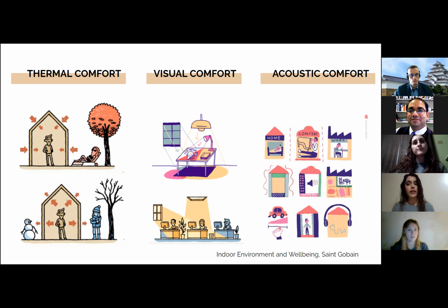Then acoustic quality depends on how well sound sources are controlled. To achieve acoustic comfort, you must first make a good design based on a complete site analysis. However, in the end, the acoustic performance is in the hand of the finishes. In order to obtain a quality acoustic space, special care must be taken when selecting technologically advanced materials in order to moderate noise levels. Now, visual comfort.